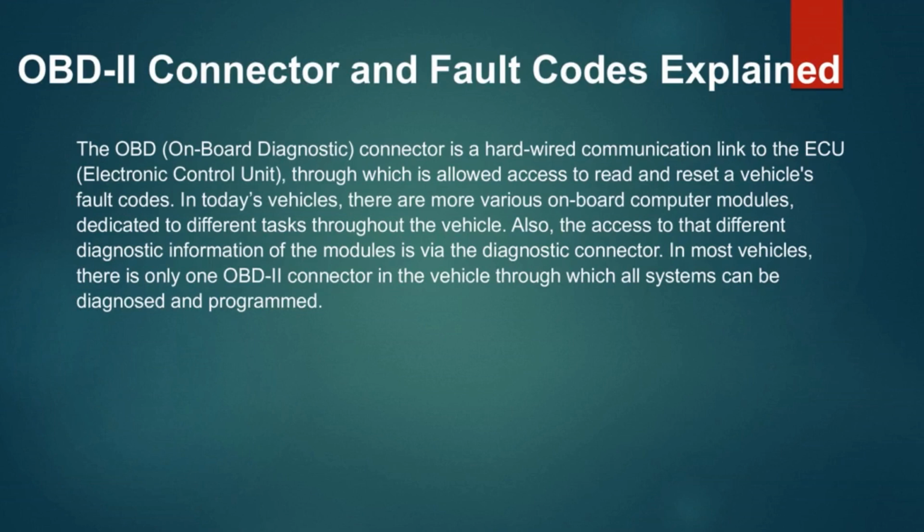The OBD, onboard diagnostic, connector is a hardwired communication link to the ECU, electronic control unit, through which access is allowed to read and reset a vehicle's fault codes.